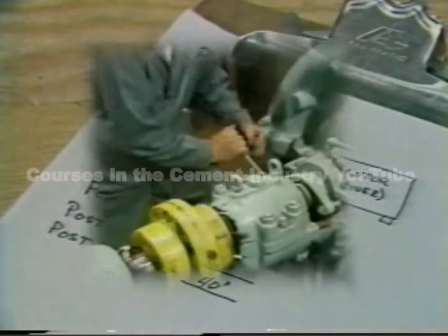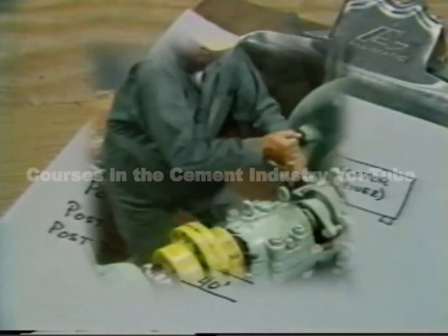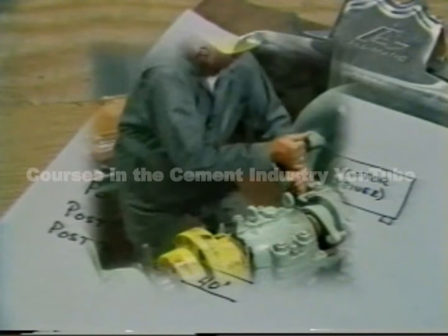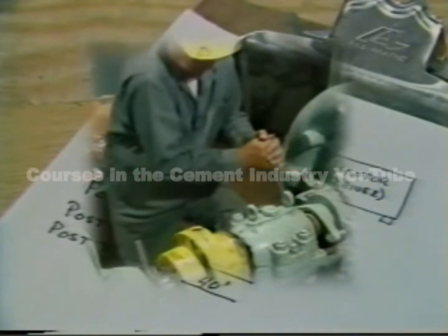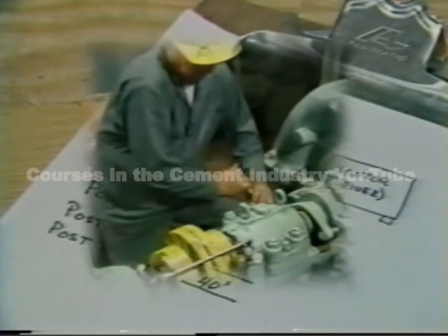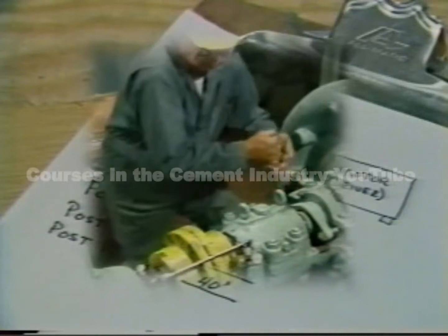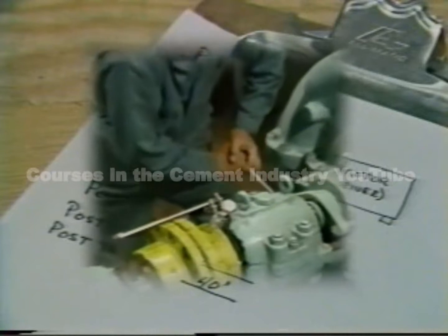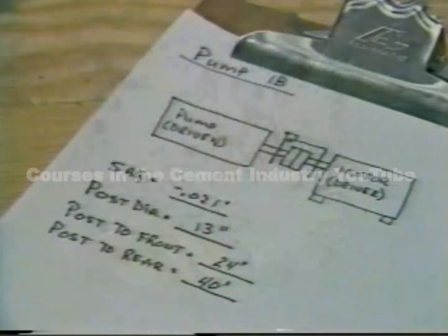Finally, the shaft was rotated 360 degrees to check that the dials return to zero. If they don't, it will mean either a loose mounting or shaft movement. When we start to gather the initial readings, you'll see another way to make sure the indications are valid during the alignment job, but that's getting ahead of ourselves. Before we go on, stop and review this segment with your instructor.